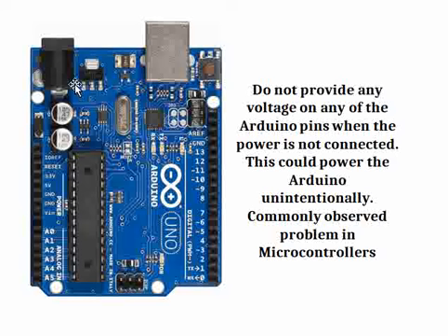For example, if the other boards are powered up and the Arduino is not powered up, and if there is some connectivity, some signal from the other boards which passes on to these Arduino connectors, there is every chance that the Arduino powers up and it might perform its actual functionality. So it's a completely unintentional scenario, right? And this problem is not just with this particular board. You see this in many of the microcontroller boards.